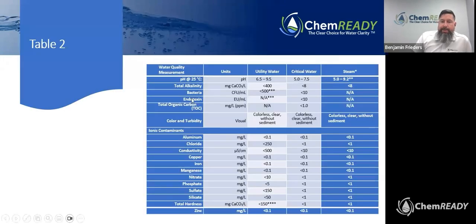These parameters, pH, alkalinity, there's another table that includes hardness, I believe conductivity is down here. There's a different table. Those are parameters you can do on site as part of your team if you've got the appropriate equipment. The only two you would need to send off to the laboratory would be bacteria and endotoxin, unless you're a hospital and you happen to have that capability, which most hospitals still send those off. But the rest of the parameters can be performed with field measurement tests.